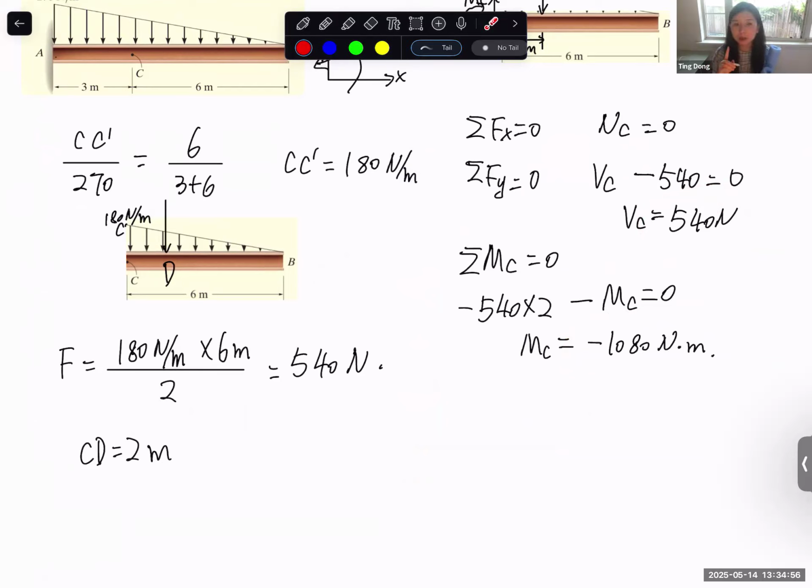That's the same thing as when you do the, I think there is one section in the statics that asks you to calculate the internal force and draw the bending moment diagram and shear force diagram. The bending moment and shear force should have their own sign convention, and when it's positive and when it's negative should be fixed. It should not depend on whether you choose the left side for the free body diagram or the right side.